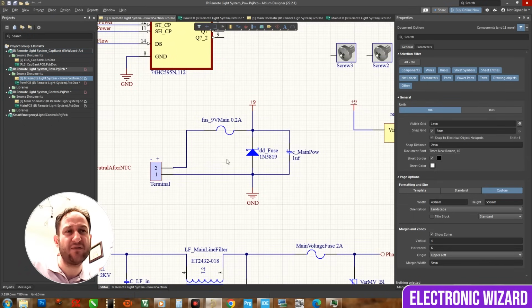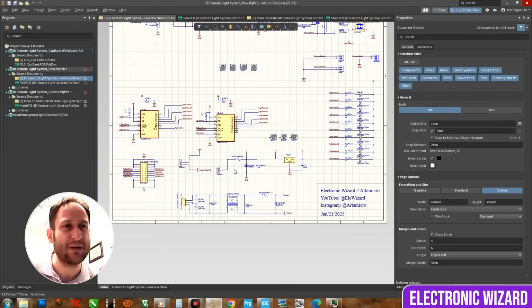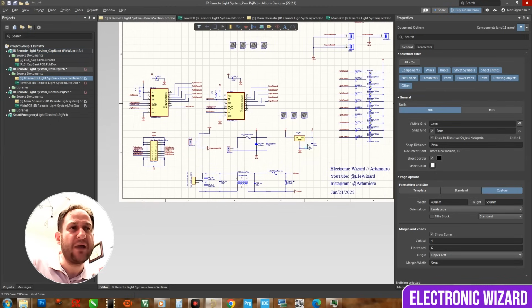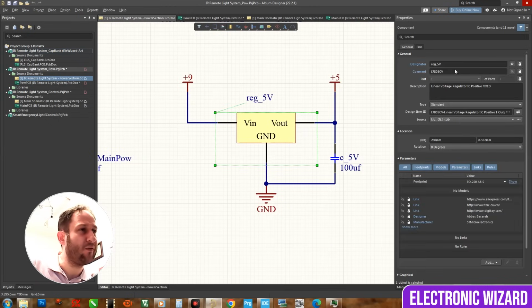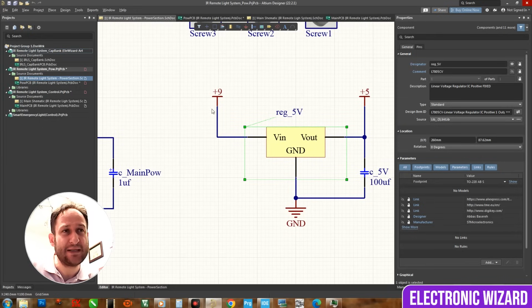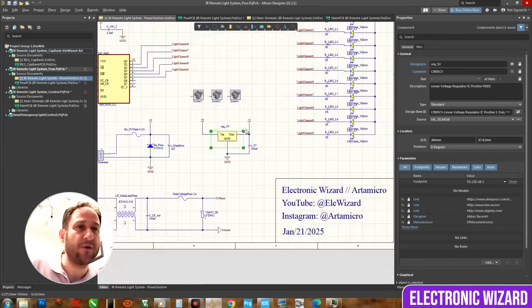And actually I have used another diode here for safety purposes, and another capacitor here for some purposes. I'm not going to dive into very small details. We have an L7805 regulator, a 5-volt regulator, here. The output of the adapter, the 9 volts, is coming through the signal to the L7805, and the output of the L7805 here is the 5 volts, which is connected to the 5-volt network here.